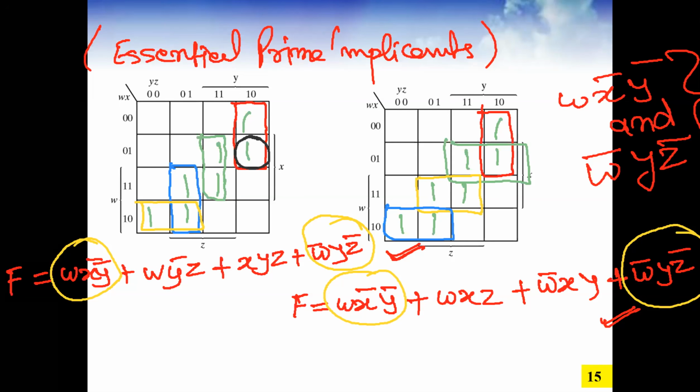On the red group, folks, you focus on the red prime implicant only, and you check. There are 2 minterms. So you check the first minterm. Can we combine it any other way? You said yes, correct? Okay. Now check the other one. Can you combine the first minterm of this column any other way, other than the red color formation? No, you can't.